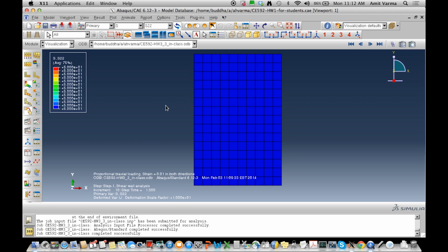So what it's telling you is that since the point has yielded, it wants to show you that the von Mises stress, which is plotted in sigma p1, sigma p2 space, is always on this ellipse. And whenever it's on this ellipse, the square root of 3J2 will be equal to 50 Ksi. And that's why it wants to show you. It understands that you're in the world of plasticity and wants to show you the von Mises stress, because that's the effective stress. You can have many different combinations of sigma p1 and sigma p2. It understands that you may have different combinations of sigma p1 and sigma p2.